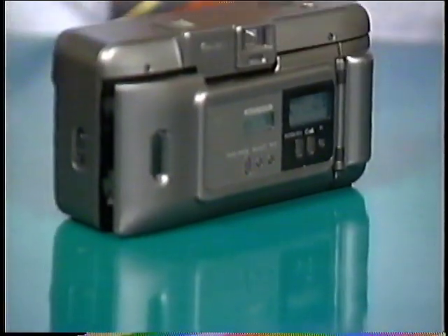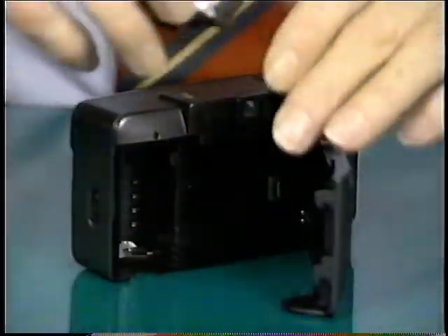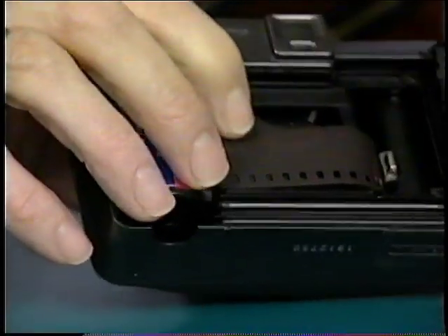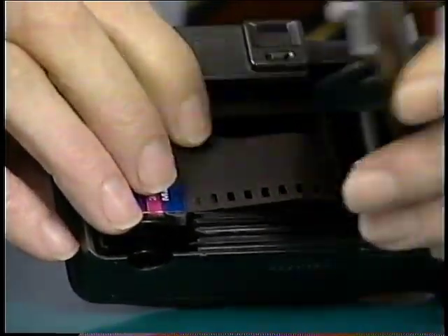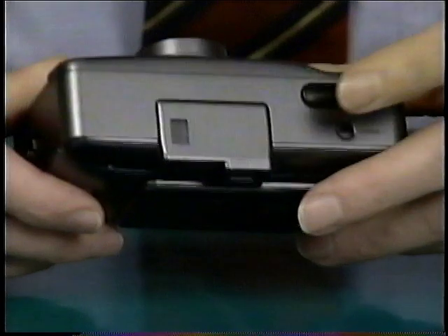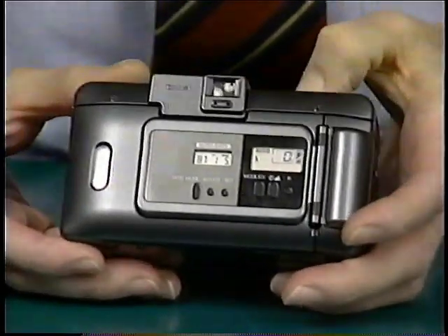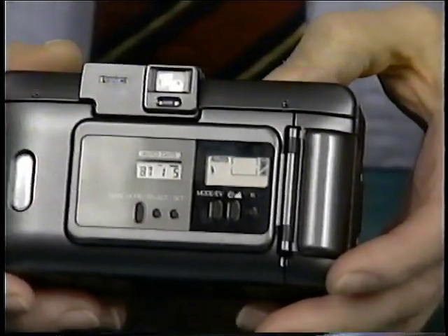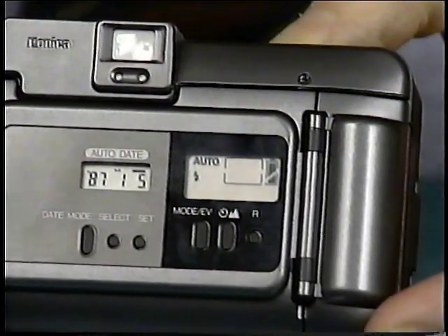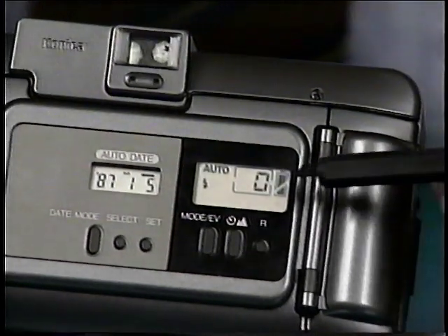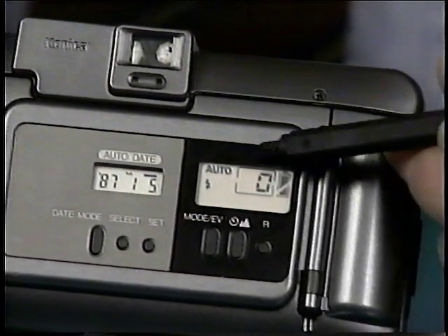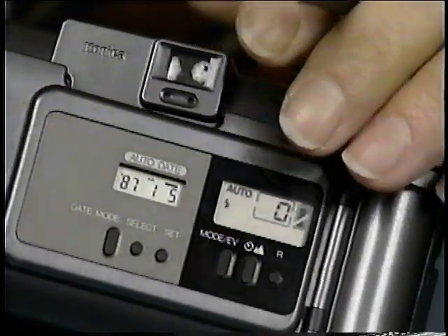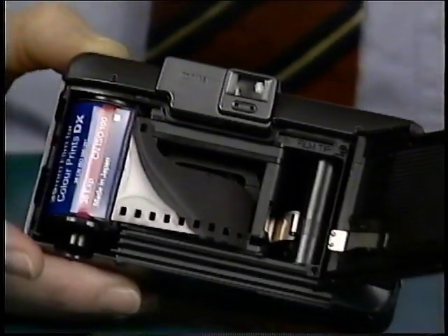If there's an operator error in film loading, or any type of film loading error, these cameras will tell you that also. For example, let's load the roll of film and not extend the leader far enough for the camera to take it up. When we close the film door and press the release button a half stroke, you hear the camera try to load, and then you'll see the flashing 0 indicating that the film did not load correctly. Most cameras will either flash the 0 or blink the 0 or the letter E, indicating empty or error. When you see that flashing, it can be reset by opening and closing the film door.